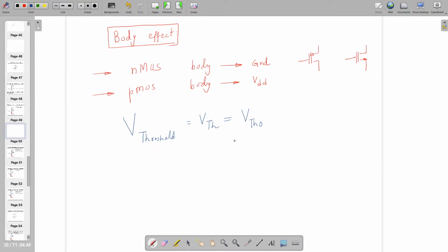Like you know that the threshold voltage of your BJT is something like 0.7, on the basis of the fact that the diode will become forward biased when VB is more than 0.7 volts, right? So we know about this, but in the case of NMOS, it might vary.